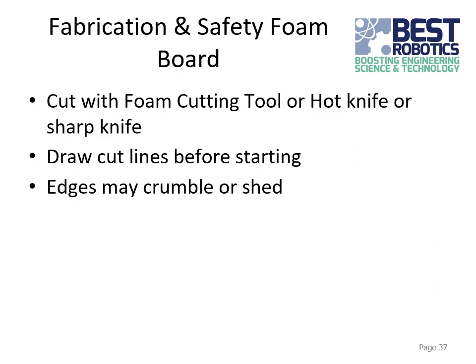For the foam insulation, if you decide to use that, there's a couple different ways you can cut it. One way is you can just use a really sharp knife and be really careful with it and go slowly. There's also something called a hot knife that basically melts through the insulation as you go. Just make sure you're being safe with that. Work with your mentor to make sure you're using it properly.